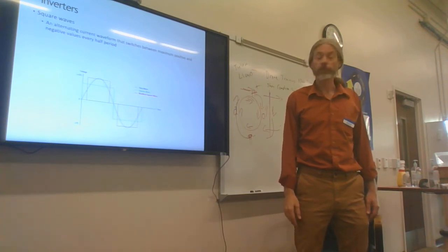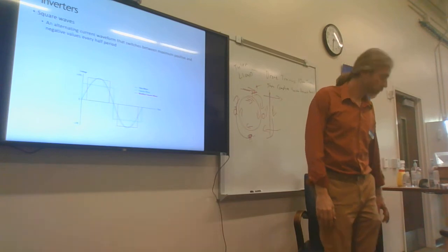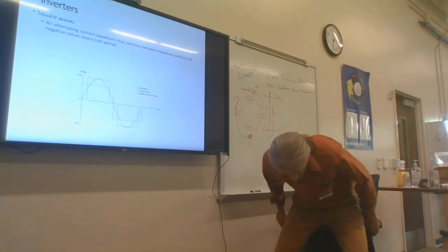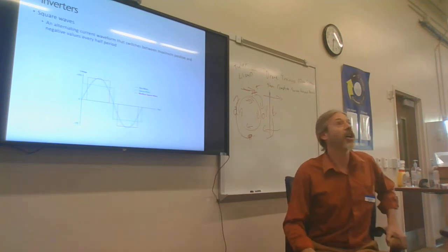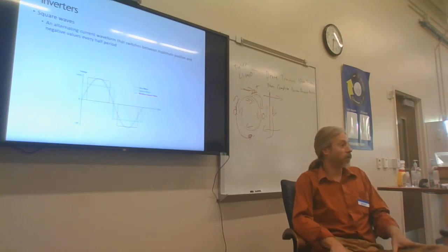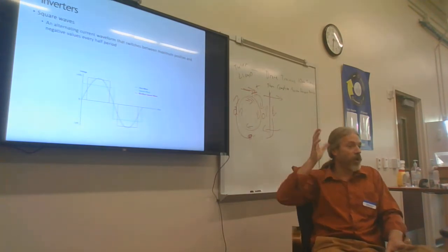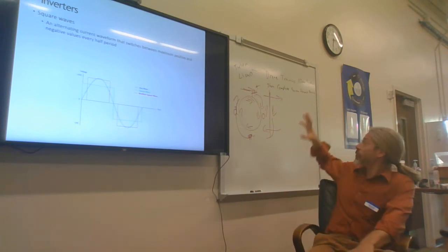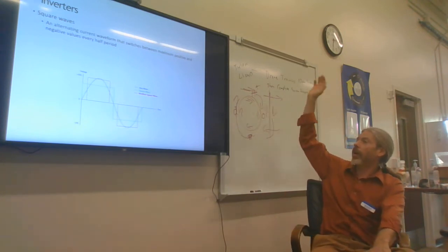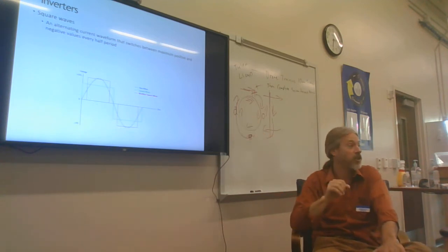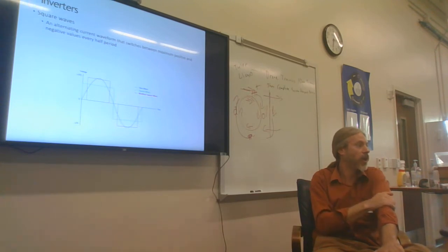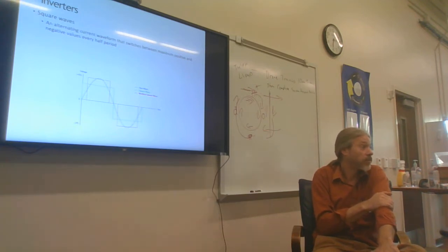So with square wave, I think I'm remembering that it can damage some of the appliances and stuff, right? Absolutely. Even a modified square wave can damage induction appliances, induction motors. And so if you are trying to create rotational energy, it is very, very necessary to have the true sine wave for an efficient rotational energy production. Otherwise, you're going to have losses, significant losses. Those losses show up as what? Heat.